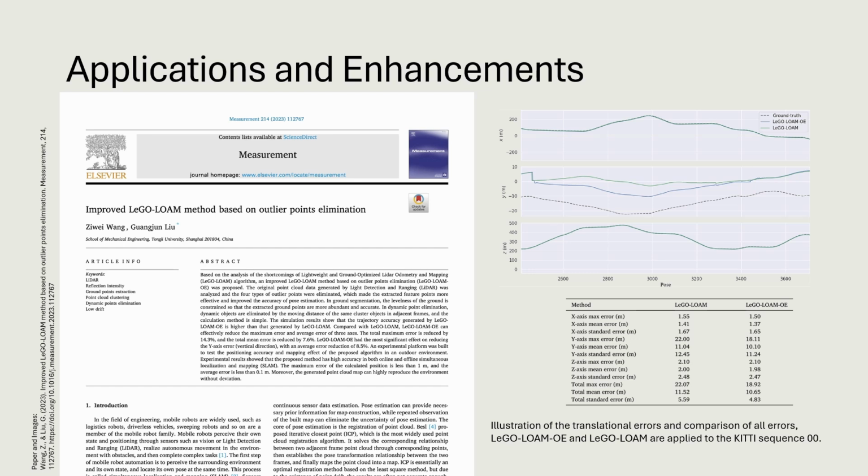elimination. The advancements are implemented in the segmentation and feature extraction steps. Overall, 4 classes of points are eliminated: points which are too close or too far from the LiDAR scanner and points which belong to moving objects are filtered during the segmentation step. Points whose reflection intensity or distance is significantly higher or lower than those of the neighboring points, and points which are located on a plane with an angle near 0 or 180 degrees to the LiDAR device are then eliminated after the feature extraction.